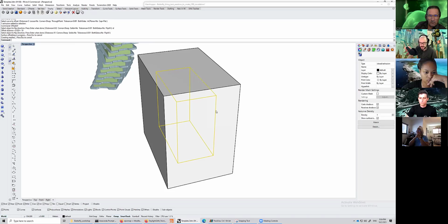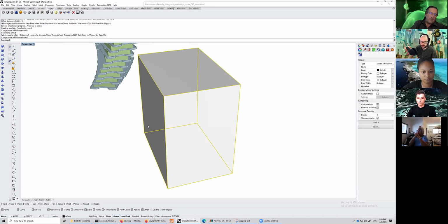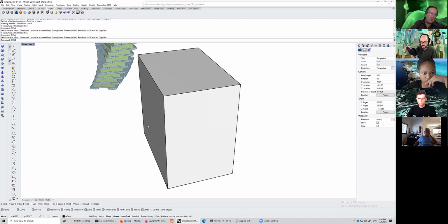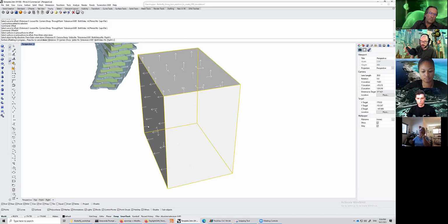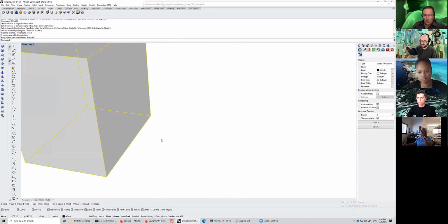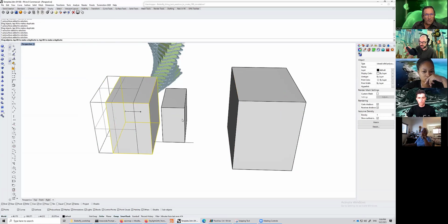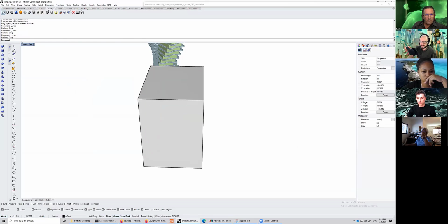We care because we will have pedestrian areas and we care about this being more accurate. And then you can put more levels here. So you can say, okay, now outside of here we have another box, and I will put them on the side so we can see. So around this box, refine twice, and then around this box, refine once. And imagine these boxes are overlapping. I just broke them out so that we can see them. So these are the areas.